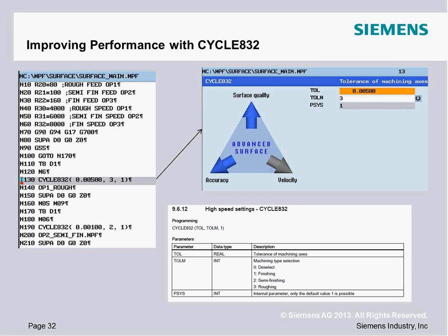In legacy-based controls, you have to program a lot of this stuff discretely, and we would find inconsistent results on the machine tool because a lot of times guys were just triggering the wrong cycles and didn't know when to leverage which cycle. So we've taken a lot of that out of the scenario by putting it all in the back end, and you just tell us, hey, are you roughing, finishing, semi-finishing, and what's the tolerance. This way, we also don't deal with cases where the guy's calling up a legacy cycle and should be using a newer one. So it kind of takes care of it.